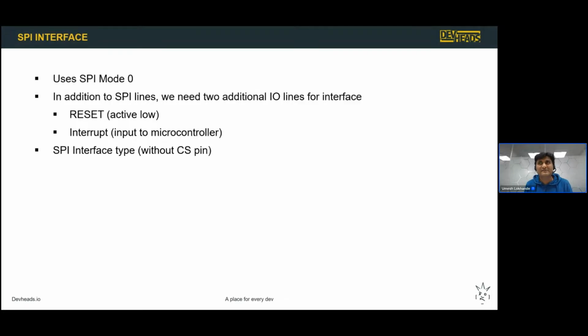What it does is it allows you to connect the W5500 with fewer pins, but you have to sacrifice other features. You can't connect more SPI devices to the same SPI bus, and that's not really good. But it does support it in case somebody wants to build a solution where they are really tight on pin counts. Then when you write an SPI interface for this chip, you have to make sure the MSB,